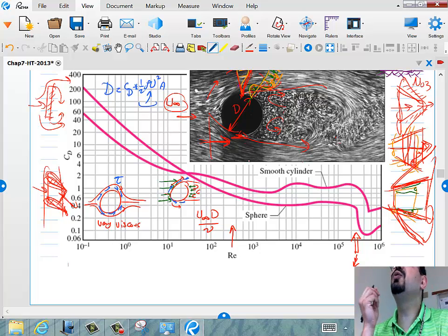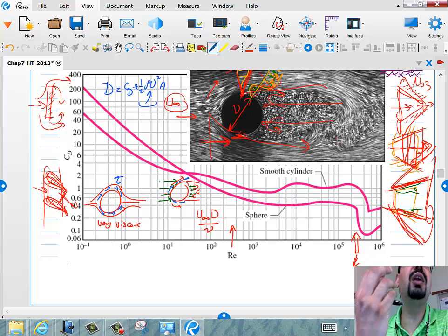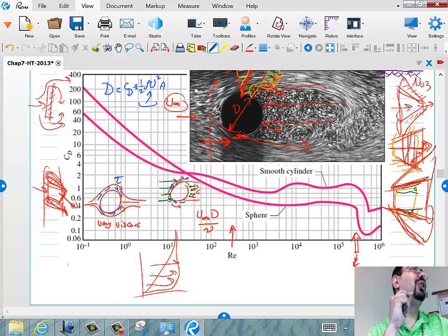How can we prevent this from happening so soon? How can we convince the flow to keep going even more before he separates? If only we can boost this kinetic energy near the wall. If only we can make our velocity profile a little bit stronger, have more momentum in it. So what can make the velocity profile more full near the wall? What I'm saying is that I don't like this velocity profile. I wish I could have it like this. See, you have more kinetic energy near the wall. Excellent. Or basically, make the flow turbulent.